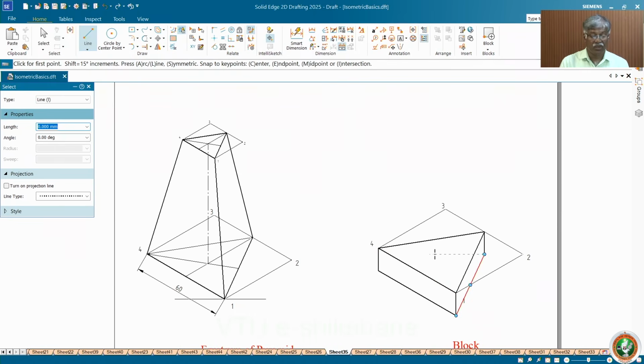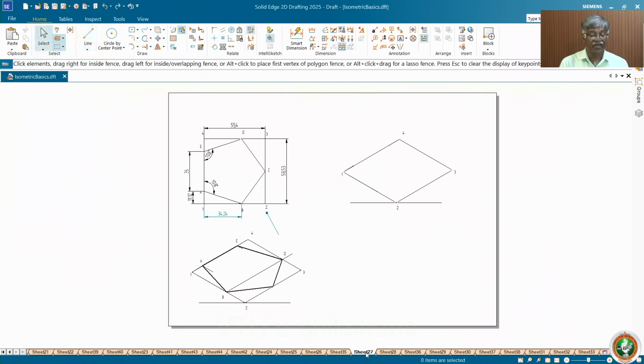triangular shape. Now let me take pentagon. So you draw pentagon in any orientation. If the situation demands, you draw in that way. For example, in top view they say one of the base edges is perpendicular to VP, or one of the lateral surfaces is perpendicular to VP for the pentagonal prism. Then you have to do this. Otherwise, by default you draw this. Either this edge can be on this side, right side, and vice versa. So you can do it.